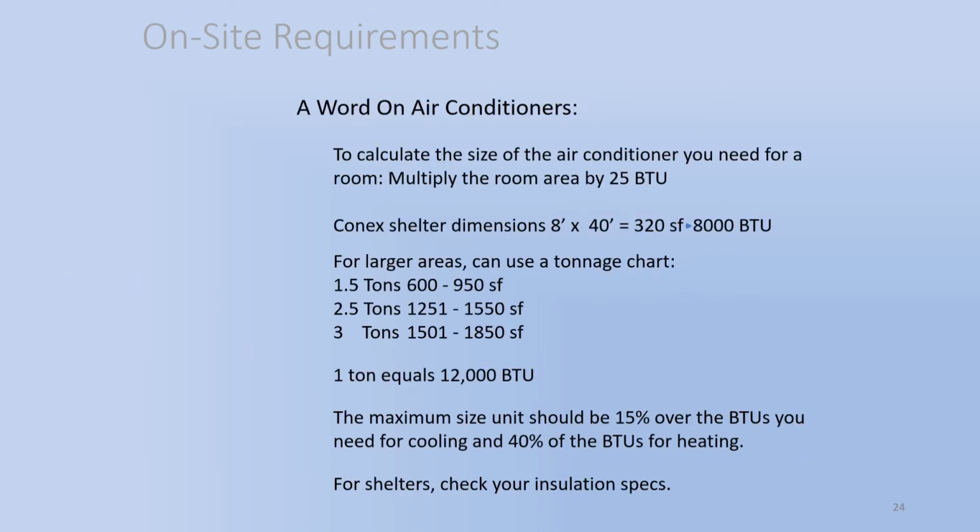And now I'd like to share a little bit of research on air conditioners. I've done plenty of reading on the internet, so that kind of makes me an expert. Not really. However, the first rule of thumb that I discovered was to multiply the room area by 25 to get the number of BTUs to get adequate cooling for that space under different weather conditions.